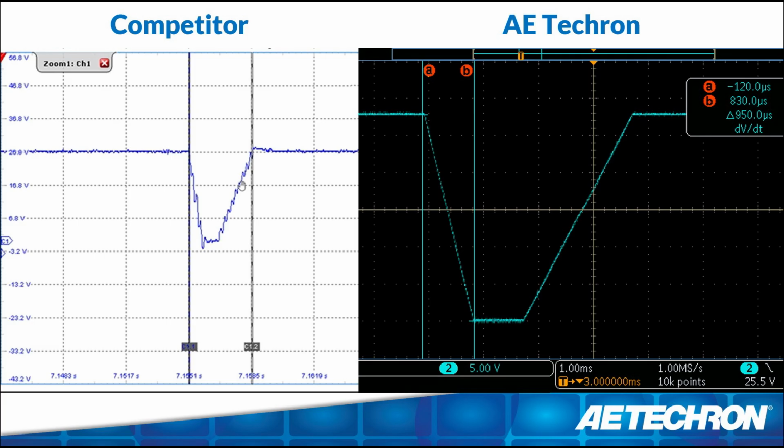Well, a lot of the methodologies used by some of the power supply manufacturers who perform these waveforms is that they'll chop these things up into small little bits. And instead of having a nice, smooth transition from one point to another, you end up with these rather ragged lines that you see on the screen here. It's maybe some overshoot, like the very bottom of the, as it reached the bottom of the waveform, it kind of overshot a little bit. And then again, another stair step coming back up. The whole thing is a little bit noisy. It's not a clean way to do it.